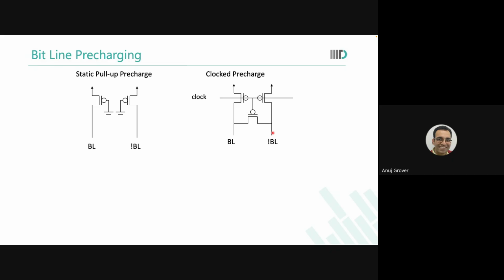So I will turn the precharge off and then I will turn the write driver on. Same cycle. Next cycle, why? The same operation, there's a sequence of, so look at it like this. Did I select a word line in one cycle and then read in the next? No. In one cycle itself, word line got selected, bitline got discharged, sense amplifier came, and I got the output.